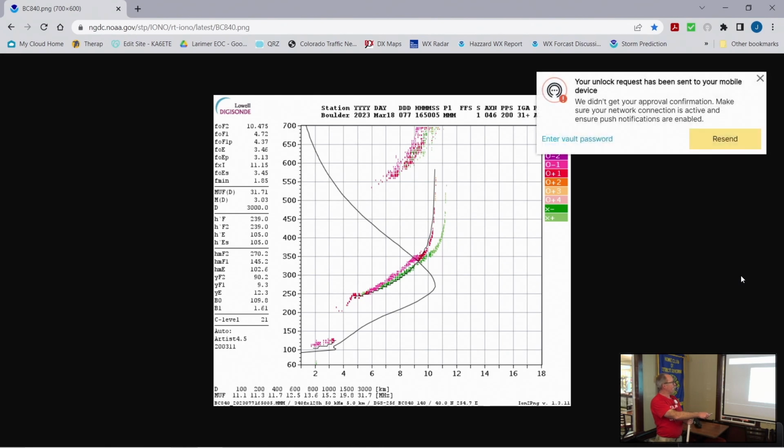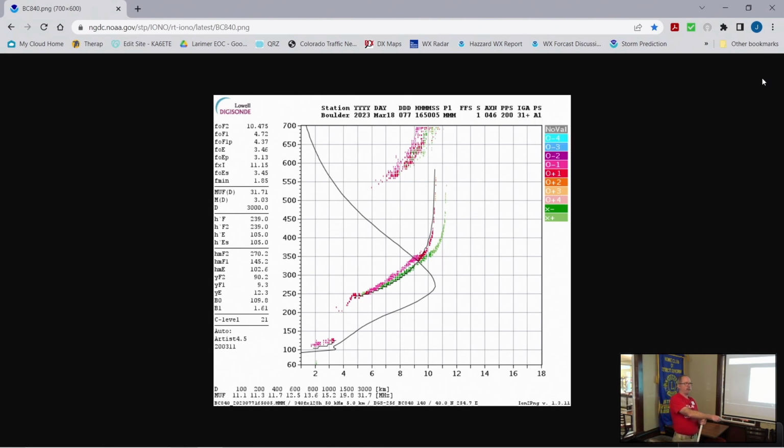We don't have a band at 13 megahertz. The military does, the government does, and using X mode, they could use 13 megahertz right now. That's about as high as I've seen. I've seen the O mode, this red, go to 13, and that's as high as I've seen it. Right now, on 30 meters, we could use 30 meters, but it would be sketchy because it's hitting this region that's really moving around. So there is no 20 meter NVIS.